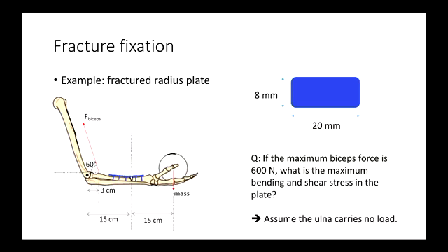Alright, so now we want stress, so bending stress. Bending stress is sigma equals My on I. You seen that before?